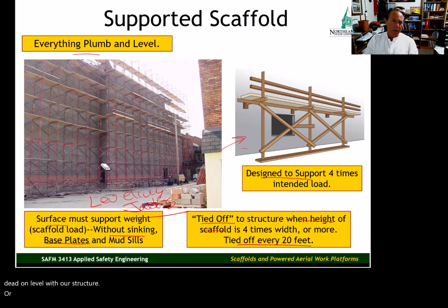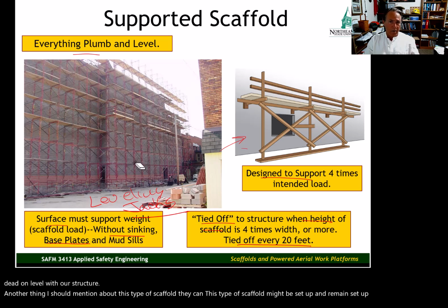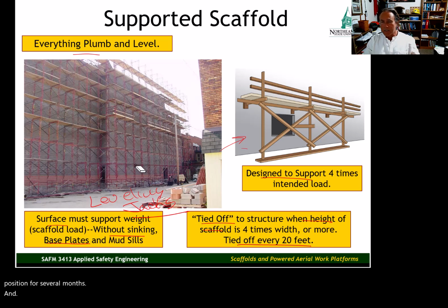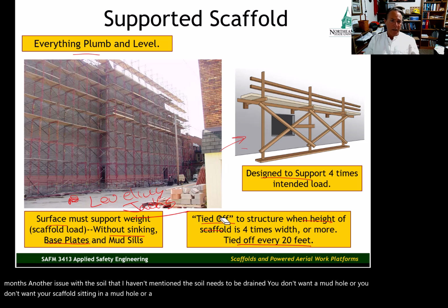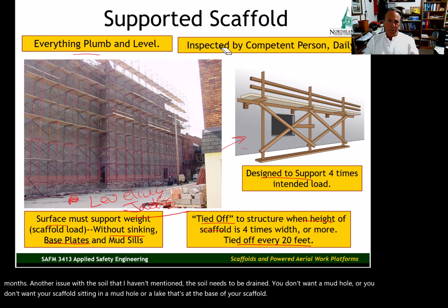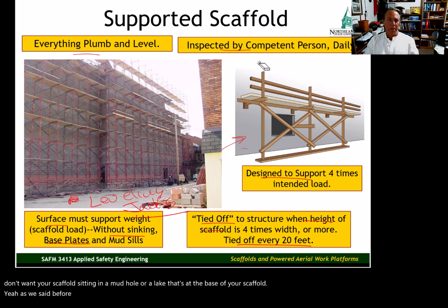Another thing I should mention about this type of scaffold, this type of scaffold might be set up and remain set up in position for several months. And it's important that it be built right if it's going to be sitting on the ground for several months. Another issue with the soil that I haven't mentioned, the soil needs to be well drained. You don't want your scaffold sitting in a mud hole or a lake at the base of your scaffold. Again, as we said before, inspected by a competent person daily.